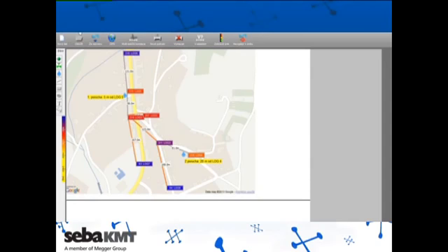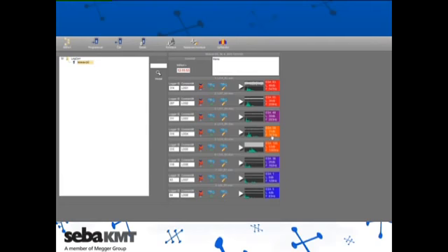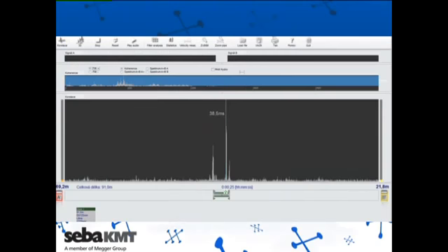If we look at the results of the SebaLog Core multi-correlator, we see that the leak is located between the sensors 3 and 4 in a frequency range of around 700 Hz. Now, if we look at the result of the Correlux P250 PC correlator, two correlation peaks are clearly recognizable. This with a broadband setting of the frequency filter.